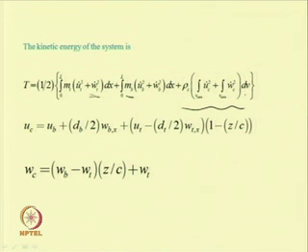So, rho_c dV is the mass, where dV is the volume, and it is multiplied by the axial velocity, u_t dot, and this is the transverse. So, this is due to axial displacement and this is due to transverse displacement, taking the velocity terms. So, one can write the kinetic energy of the system.